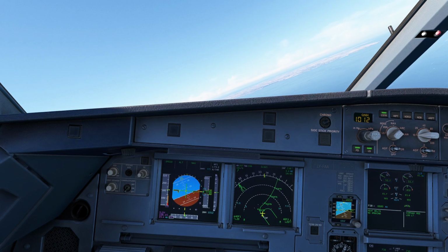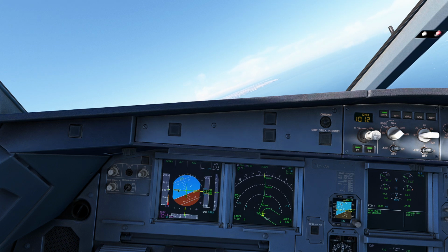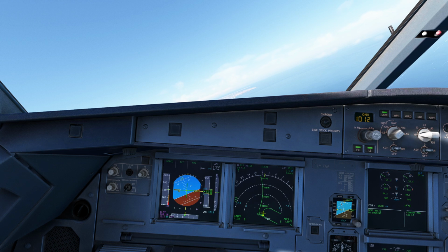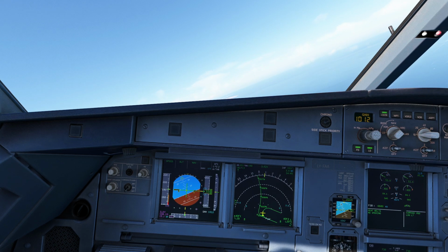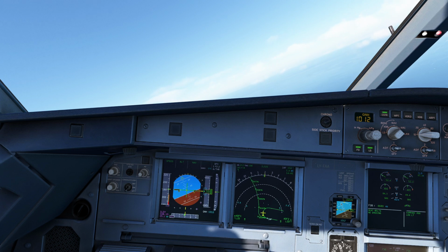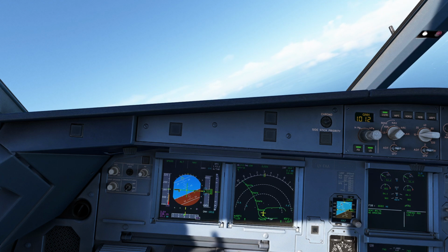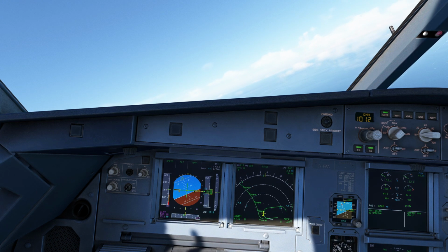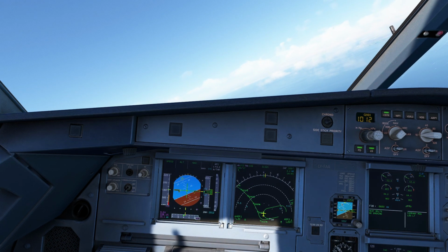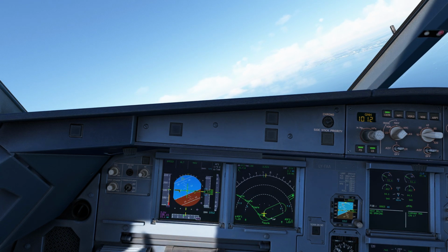If you are visually correcting the flight path, the flight director cues become misleading, trying to pull you back toward the localizer course. Airbus and most airline SOPs recommend turning off the flight director when you go visual below minimum or decision altitude and you need to manually align with the runway, as in offset ILS or circling approach.